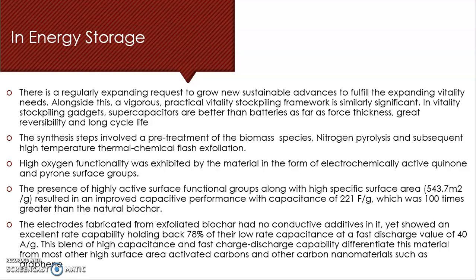The electrode fabricated from exfoliated biochar had no conductive additives in it, but yet it showed an excellent rate capability, holding back 75% of the low rate capacitance at a fast discharge value of 40 amperes per gram. This blend of high capacitance and fast discharge capability differentiates this material from other high surface area activated carbon and other carbon nanomaterials such as graphene.